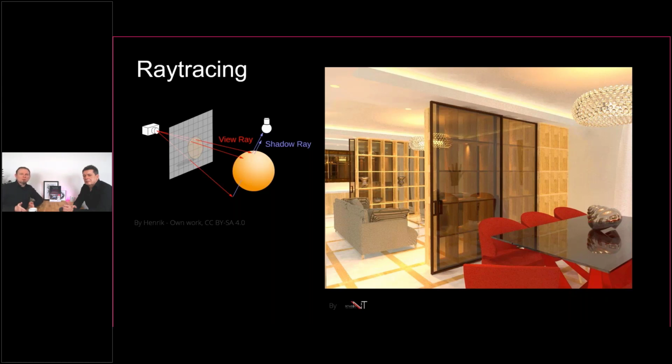You can use ray tracing without radiosity and vice versa. And you can also have all of them, and you have all of them in the output. You can compare ray tracing with radiosity and with an Enscape impression, not in values, but as an impression, and compare the different calculation cores. A lot of options, I know. But this is the best flexibility you can have in lighting design, to choose what you are going to need. And that's also the reason why you cannot just switch off the ray tracing core in favor of Enscape, because there are values you can calculate.